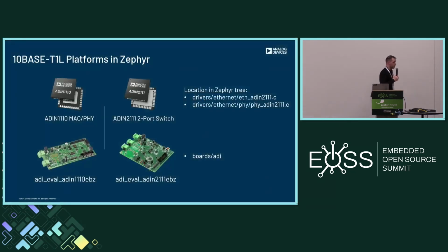There is currently support for two of ADI's 10BASE-T1L transceivers within Zephyr. These are the ADIN1110 MAC-PHY as well as the ADIN2111 two-port switch. These transceivers, along with their respective evaluation kits, are supported within upstream Zephyr. You can see their location in the drivers directory.